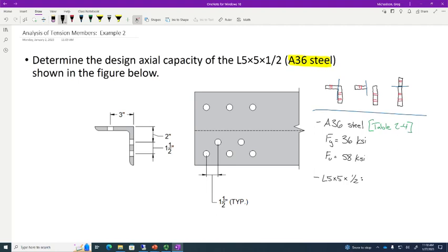I haven't seen very many bridges, at least in our neck of the woods, that use 80. You might find that out west for some really, really long spans. But 50 and 70 are probably the most common that you would see in bridge steels. But yeah, the most direct application I can think of for something that high is columns in really, really tall buildings.